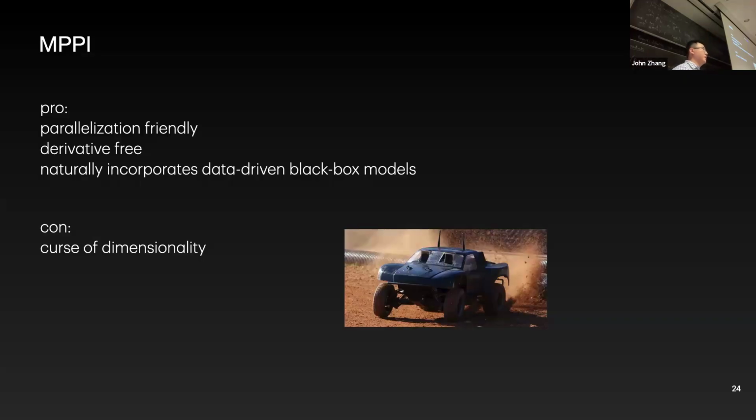You basically control the steering, acceleration, that sort of thing. And you're also dealing with pretty complicated dynamics that are hard to model, so you can think about learning the interactions between your wheels and off-road terrain like dirt and mud. MPPI can do that very naturally.